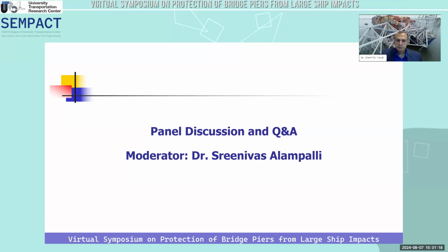And so the impact forces were about the same, based on his research, from a loaded bulk carrier with no ballast in the forepeak of the ship versus a ballasted bulk carrier with water in the bow of the ship that was strengthened. And so that's why at the end of the day in AASHTO, we didn't differentiate between loaded and ballasted.